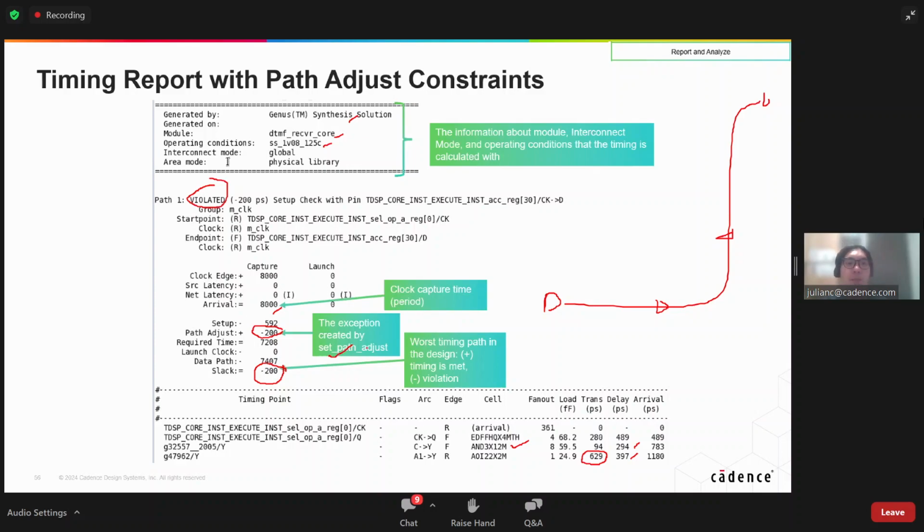So you can see here, by just changing some constraint, it causes a violation, and now the tool has to decide to optimize it. They have to optimize it either by sizing, mapping, selecting a better logic cell, or maybe do some ungrouping, optimize it further, instead of using AOI, maybe use some other type of logic, some logic structuring and so forth. So just one constraint update can cause a change in result, and the change in result causes the tool to use another strategy to do optimization.